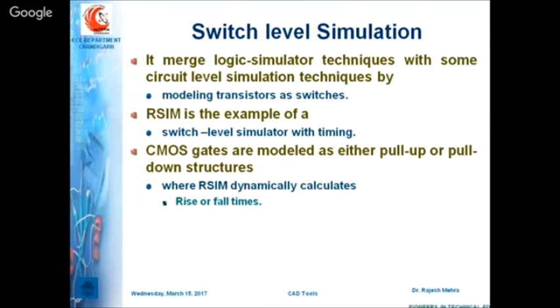Second is your switch level simulation, where you can use transistors as switches, right? RSIM is one example of a switch level simulator, and here you use CMOS logic. Pull up and pull down transistors are used to calculate the rise and fall times.